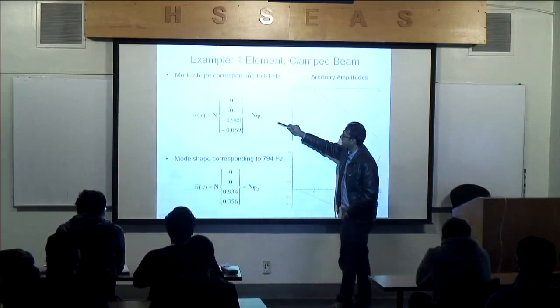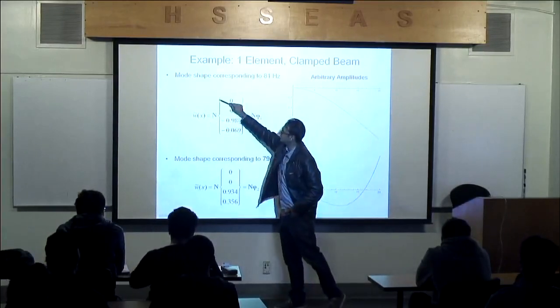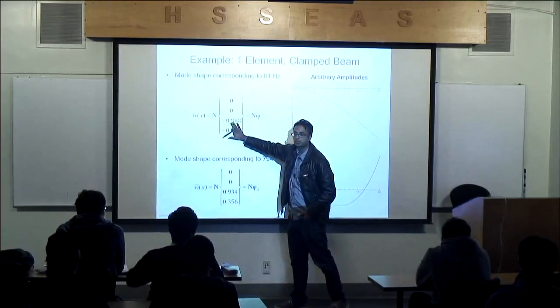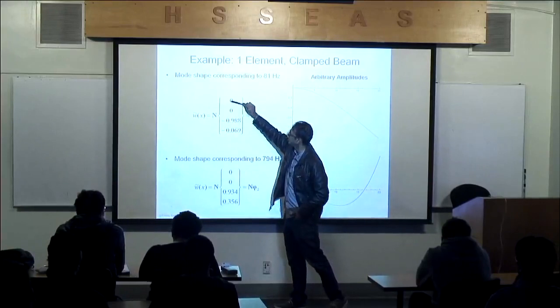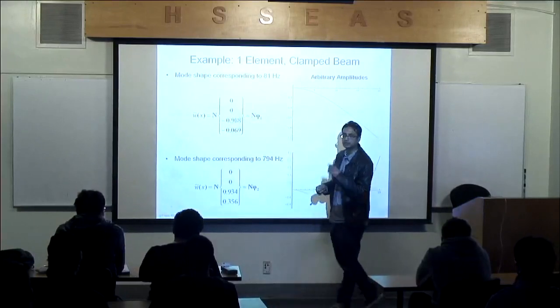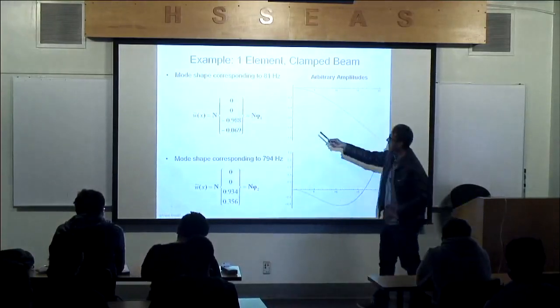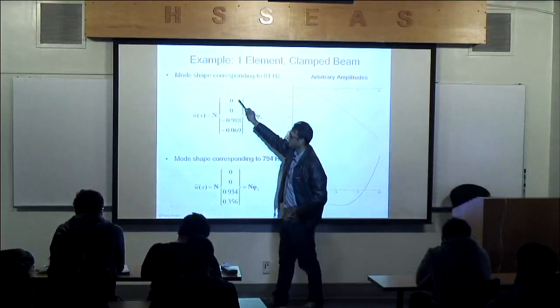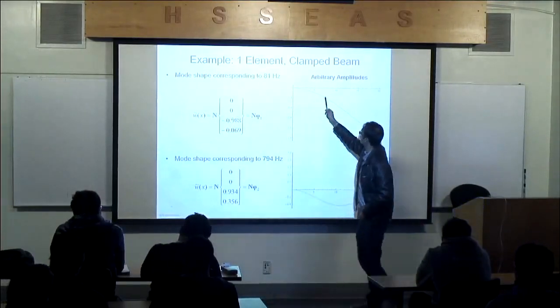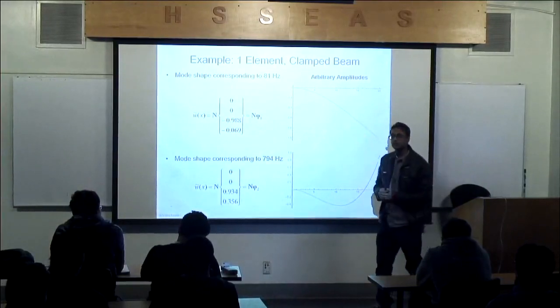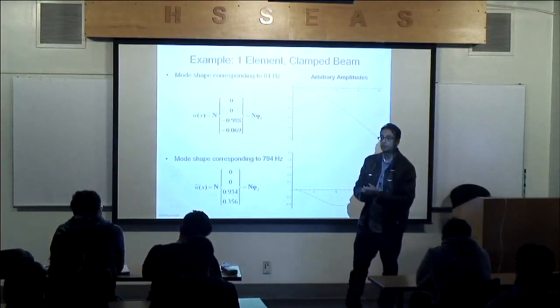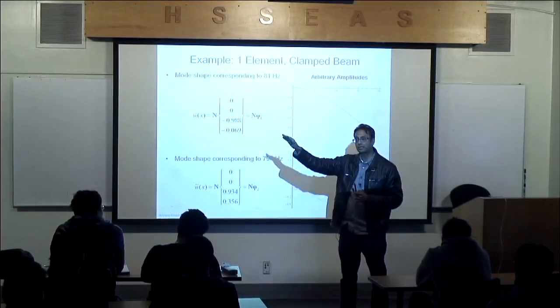Okay. So then I'm going to call this phi1 bold on purpose. I'll discuss why I'm calling this phi1 bold. But I want to remind you that phi1 bold is a vector. In this case it is 4 by 1. If I plotted this and I did it in Mathematica, what you get is that this is a shape. Okay, that's the first shape. That's the first bending shape. That's actually the first mode shape, and it's actually the first bending mode of that beam.